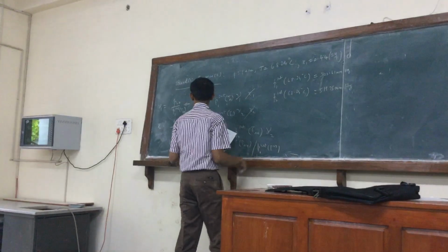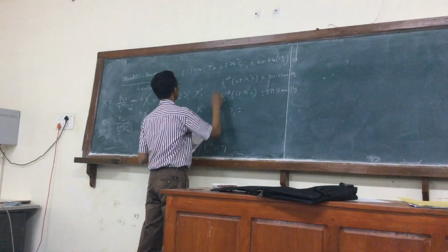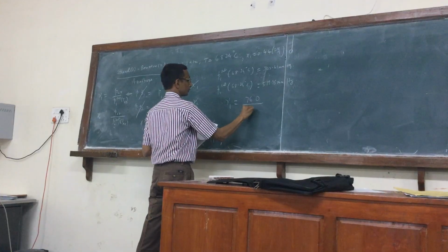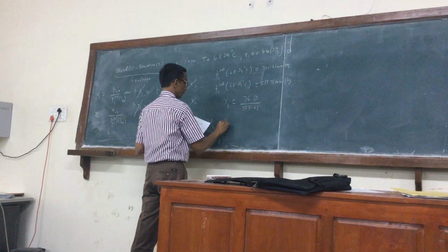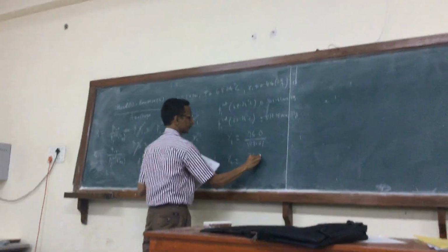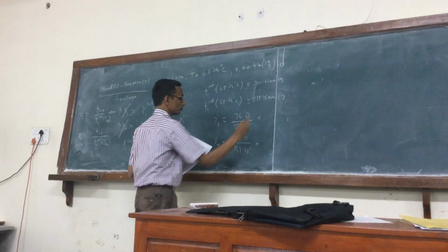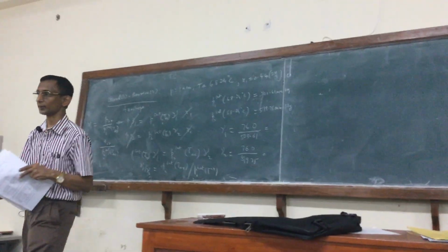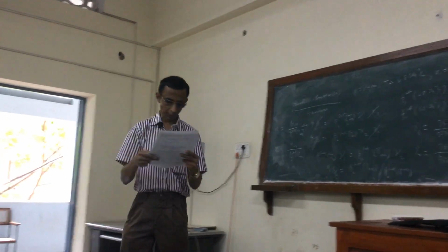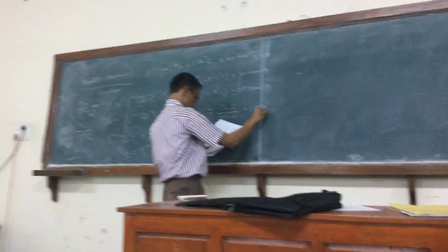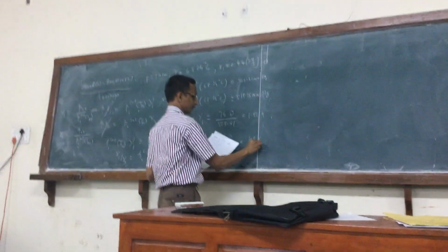And so I can get gamma 1 to be, with P at the azeotrope being 1 atmosphere, 760 by 503.61. And gamma 2 is 760 by 519.7. You can see that both of these, whatever the value is, have got to be greater than 1. Gamma 1 is 1.509 and gamma 2 is 1.462.